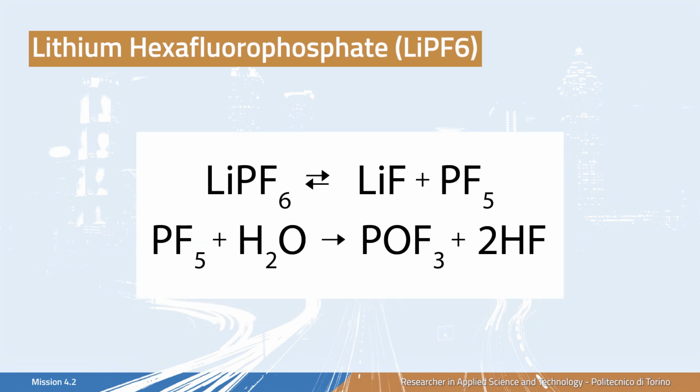However, LiPF6 suffers from moisture sensitivity, leading to the detrimental formation of HF. For this reason, other salts based on bis-sulfonyl amide anions are also being explored for the enhanced chemical and thermal stability and the possibility of operating at higher voltages.